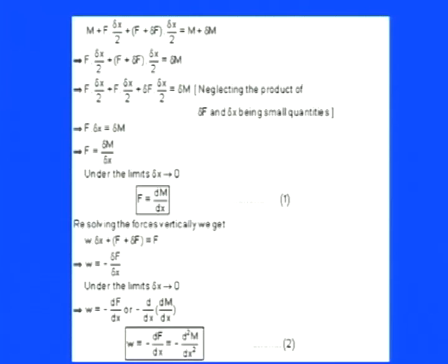Now, this analysis came when we balanced the moment equation. But now if we balance the vertical forces, you will find that we have vertical forces all along acting on this cantilever or simply supported beam. Since the load is coming from the top side, at point C it is W into dx. This is the total load coming from the top side, and the shearing forces are there on both sides: one side is F, and the other side supporting this part is F plus dF.